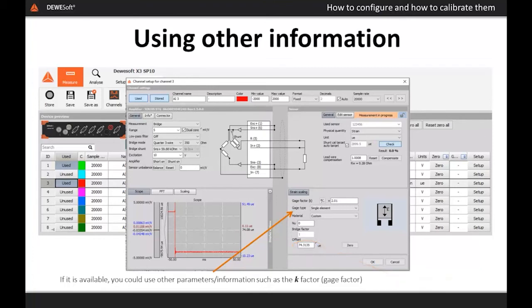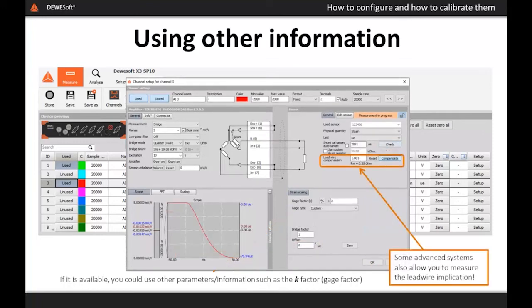You'll remember the mentions of lead wire, something that was frequently set aside as of less than great concern in years gone by. Here, as with the ability to use multiple shunt values in multiple locations, some systems also offer you the ability to manually accommodate lead wire resistance and even measure it and tell you what it is. And by the way, just as an example, the 28 gauge 6 strand is typically about 6 to 7 ohms per 100 feet.